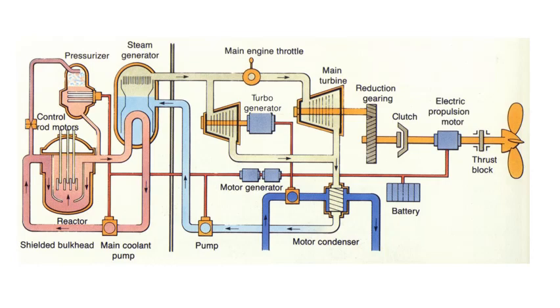The heating of the water takes place in the heat exchange unit. The steam passes through the turbine and forces the generator to rotate, producing electrical power. The generator supplies electrical energy that charges storage batteries and powers the two DC motors that drive the submarine's propellers.